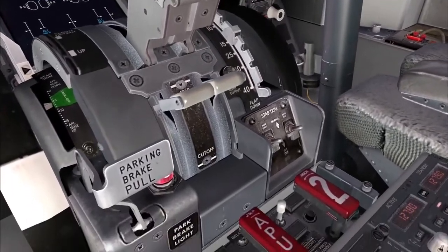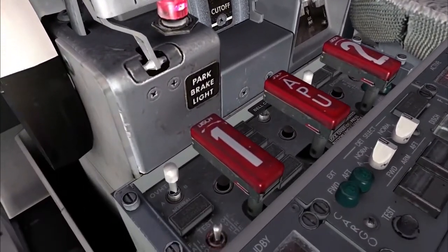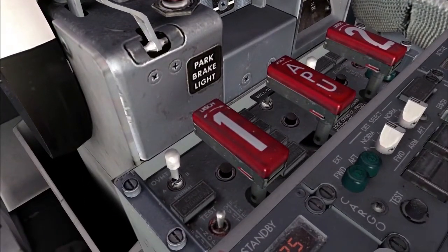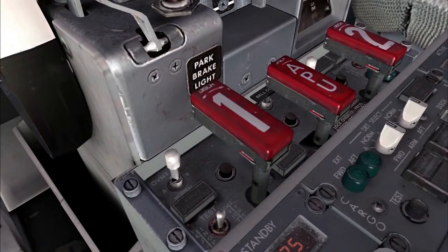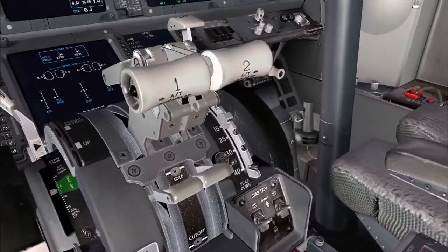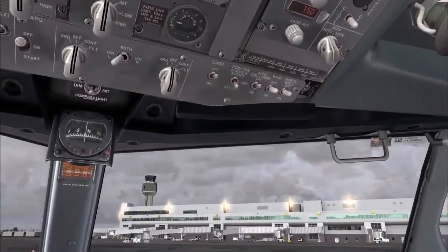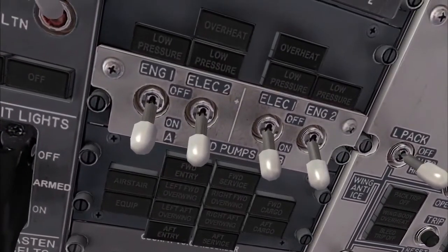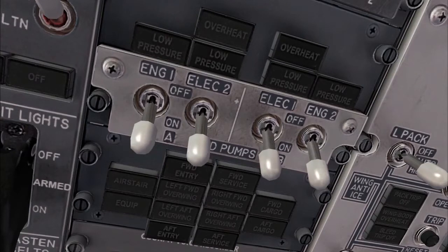When an engine fire switch is pulled, the related engine-driven pump's low pressure light is deactivated. It is a given that the pump will be putting out low pressure when the fire switch is pulled, as the engine will be shut down immediately. Crew workload is high following an engine shutdown, so the light is deactivated to eliminate the unnecessary distraction it could cause the flight crew.